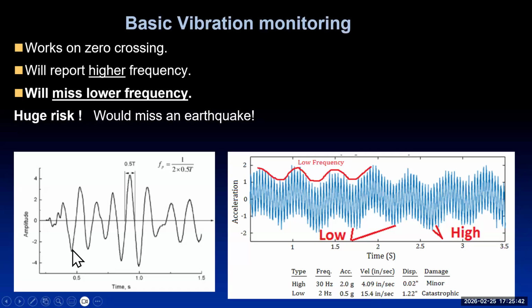And then it goes up and down on what we call the time history, and it has what you call zero crossings. It's crossing when there's like 0 Gs, if you will. It hits a peak and then it comes back the other way, and it does some sort of sinusoidal turn like this. So that's the raw time history. But embedded in that is a number of things. The one thing they look at to get the frequency of the energy, the primary fundamental frequency of this, is they do zero crossings. They say, okay, it crossed here and then it crossed here. So that time is 1/2 of what a full cycle is. And that's the frequency of response.